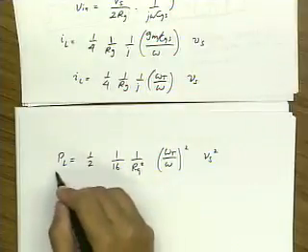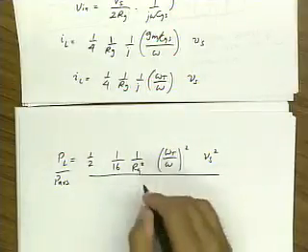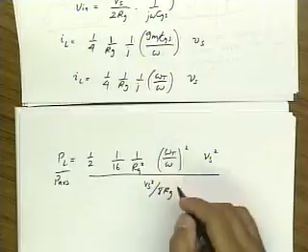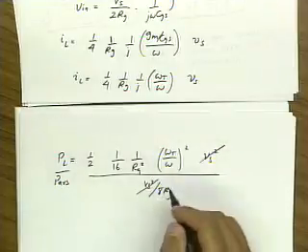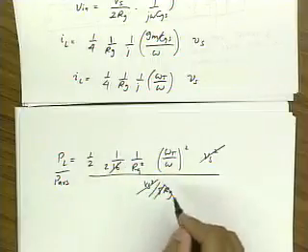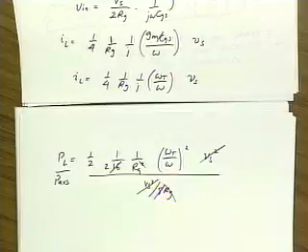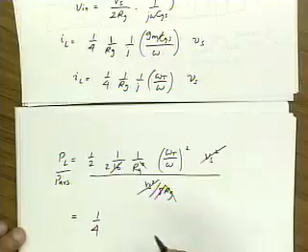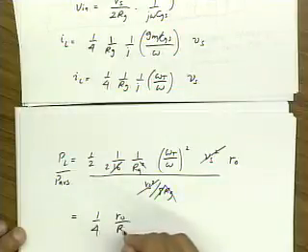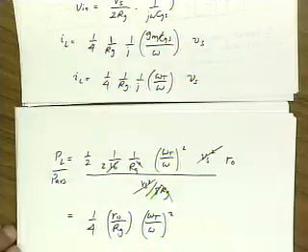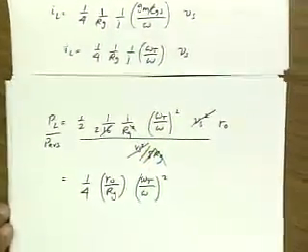And if I now divide this by power available from the source, that's Vs squared over 8Rg. And so the Vs squared cancels out. This 8 cancels out with this, and I get a factor of 2 here. This Rg cancels out with this Rg. And so my final expression looks like 1/4. Oh, and I forgot to multiply by Ro here. 1/4 Ro over Rg, omega t over omega squared. If I made a mistake, maybe you guys can catch it.